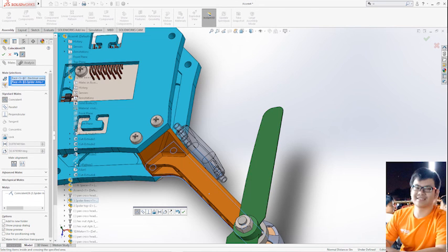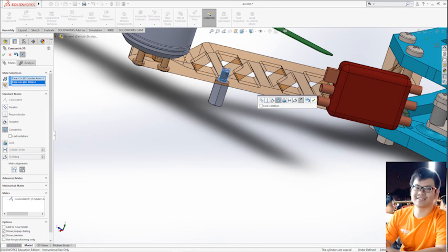Step 32. Set the electrical connector parallel to the base of the spider arm and the side of the electrical connector coincident with the side of the spider arm. Step 33. Set the tube of the pillar concentric to the hole under the spider arm and the surface of the pillar in contact with the base of the spider arm with coincident.